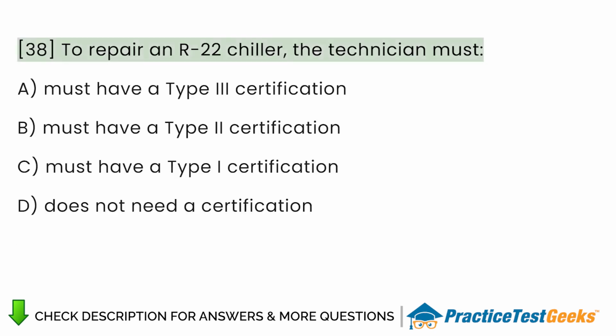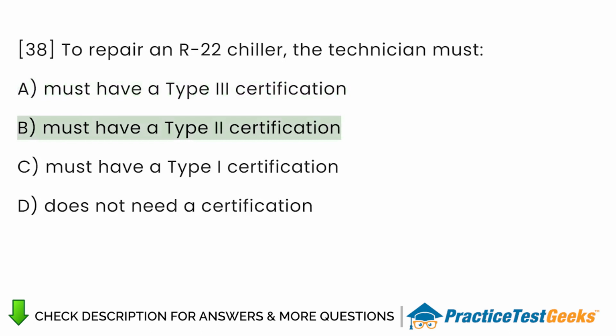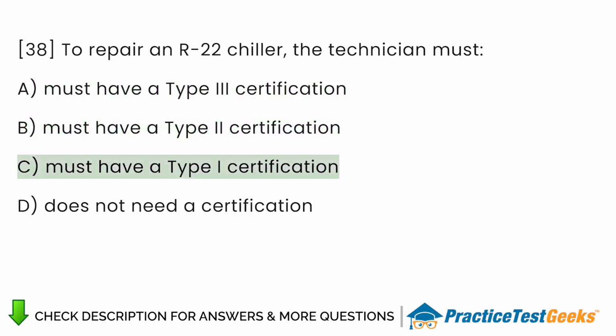To repair an R22 chiller, the technician A. Must have a Type 3 certification. B. Must have a Type 2 certification. C. Must have a Type 1 certification. D. Does not need a certification.